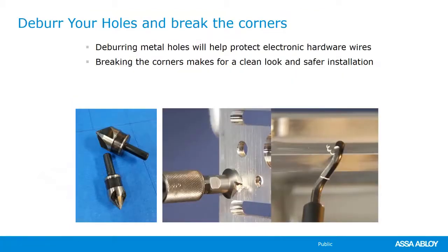We need to make sure that after we drill our holes that we deburr the holes and break the corners. That just makes for a clean install. Also, if somebody is working on the door and they're not wearing gloves, maybe we protect them from getting a cut. But there are chamfer bits, there are countersink bits, and there are these little scraping tools that do a good job of taking the corners off of material.